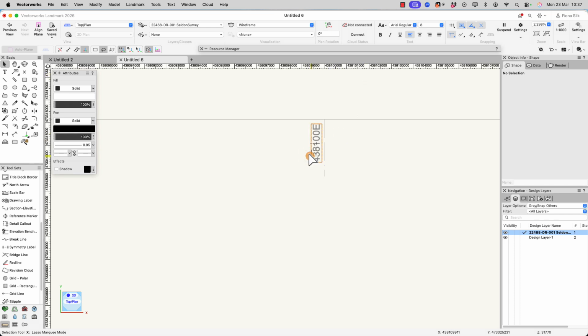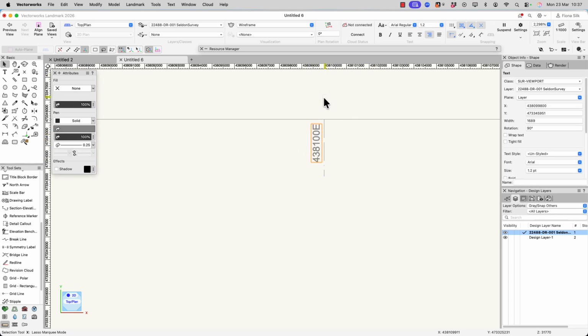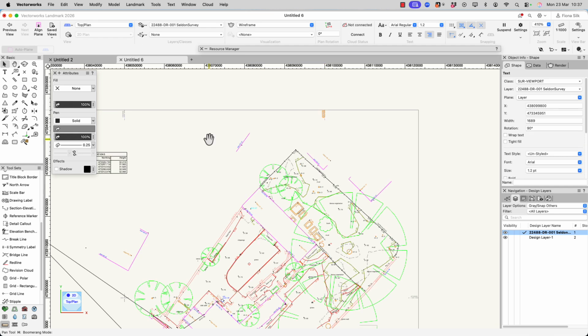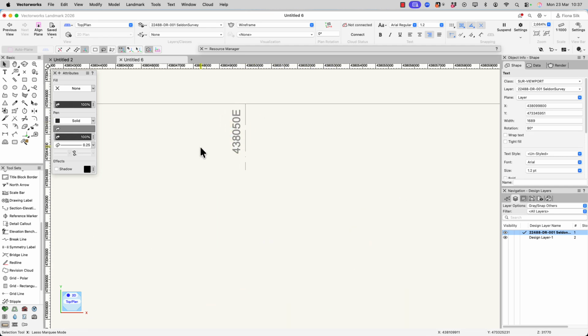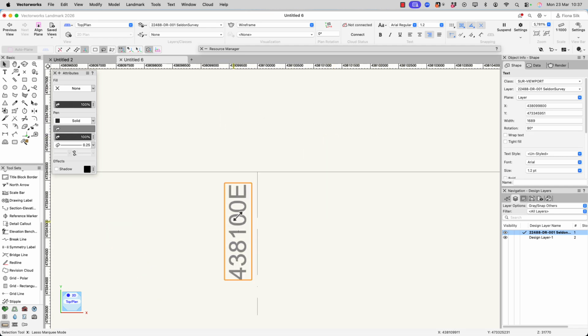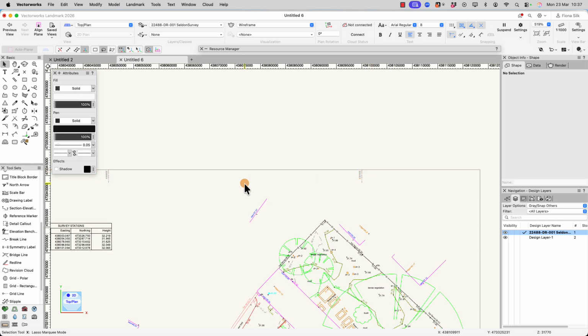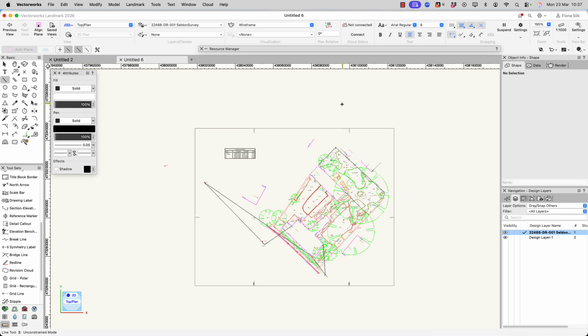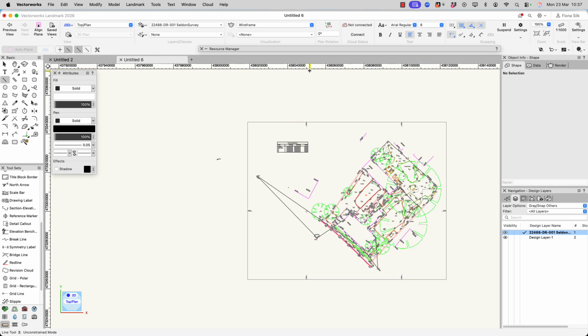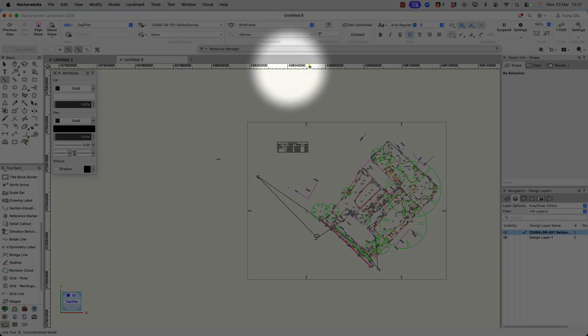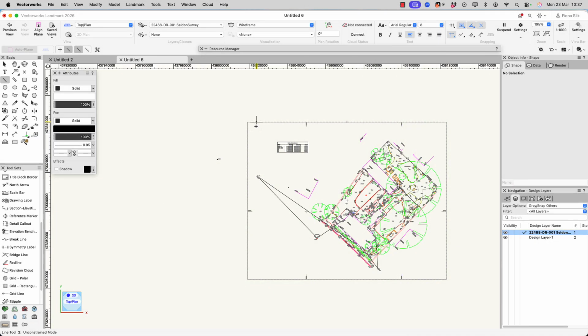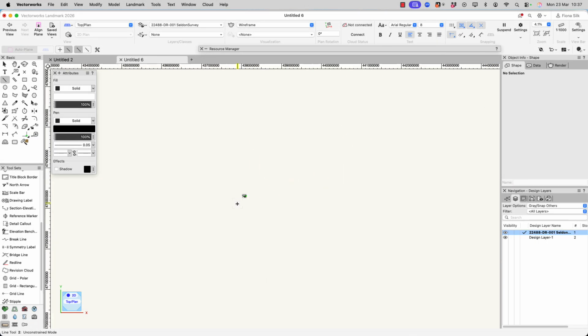But this is a site survey and it's geolocated, and you can see across the top and the sides there is a grid like this. So this is 50E, this is blah, blah, blah, 100E. So not only does that tell me the scale, so there should be 50 meters between them, which there are, 50,000 mil, but it also tallies up with the rulers at the top and the side of the page. So great, really useful. But obviously this makes the drawing far away from the 0 point, and it can make it really, really hard to work with. It can cause some kind of issues as well.